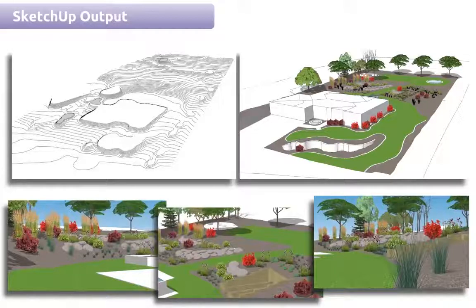Yes, it will remember, but what we do is we typically fly it in what are termed cells, or you call it missions. Basically, you're going to have your large area site that you're mapping, and you're going to break it down into missions that have some overlap. They don't need a lot of overlap, but enough so that it knows where these things are meeting up. And then you'll fly mission 1, mission 2, mission 3, mission 4, and so on.